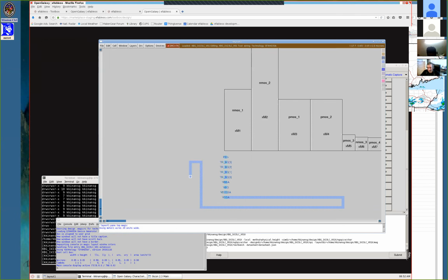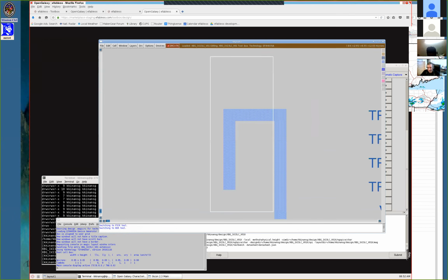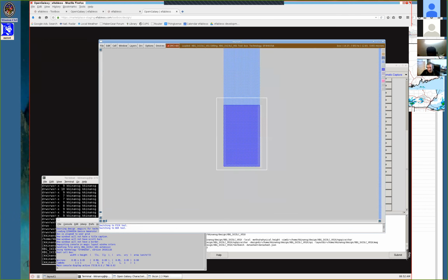Now you can use the wire tool to move between layers. However, the problem with that is that the contacts require certain surround rules. Another way to draw contacts, which I also don't recommend, is that you can just go up here, click on the metal contact layer, and when I do that, you'll see that I immediately get DRC errors because it's missing the surround rule. If you want to find out why that DRC error happened, you can always go down to DRC and say DRC report, and it tells me, okay, metal 1 overlap of via 1 is an error. I don't have metal 1.